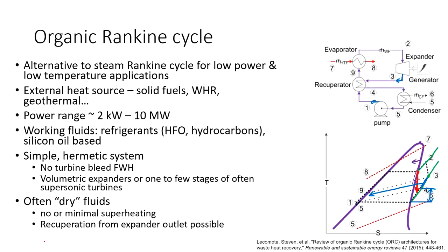Also one other feature making ORC suitable for waste heat recovery application is that the ratio of the evaporation heat and the specific heat capacity is much smaller with some of the organic fluids.